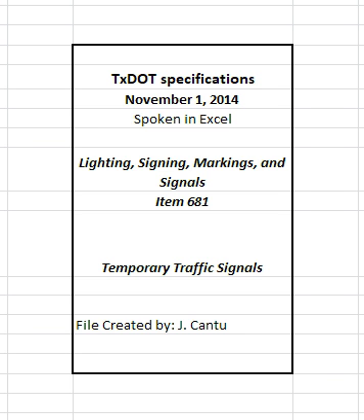3.2 Reconfiguration. Reconfigure temporary traffic signals in accordance with the plans, and within the requirements of this item, as directed. Reconfiguration is any change made to an installed intersection, including relocation of poles, controller, signal heads, or luminaires. 3.3 Removal. Remove all equipment installed for temporary traffic signals as shown on the plans or as directed in writing.